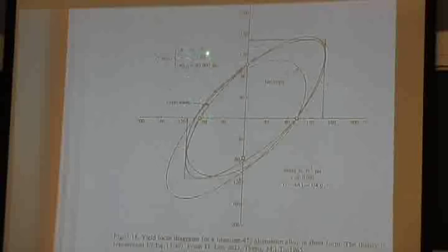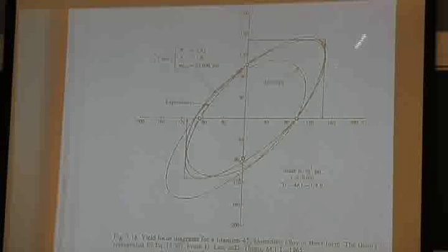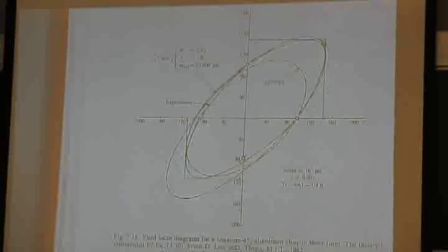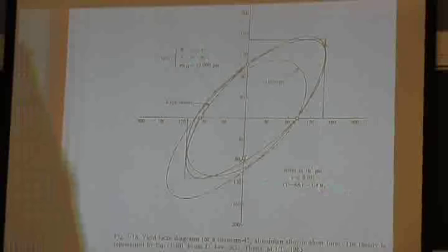The R value is 2.5. And remember, the R value could go up as high as 5. So this was not some special sheet that he got. I mean, that's for alpha titanium, that's not an exceptional value. It was titanium 4 aluminum with 0.25% oxygen. There's a lot of oxygen. Not a huge amount, but it's a little high. Okay, so why do we care?